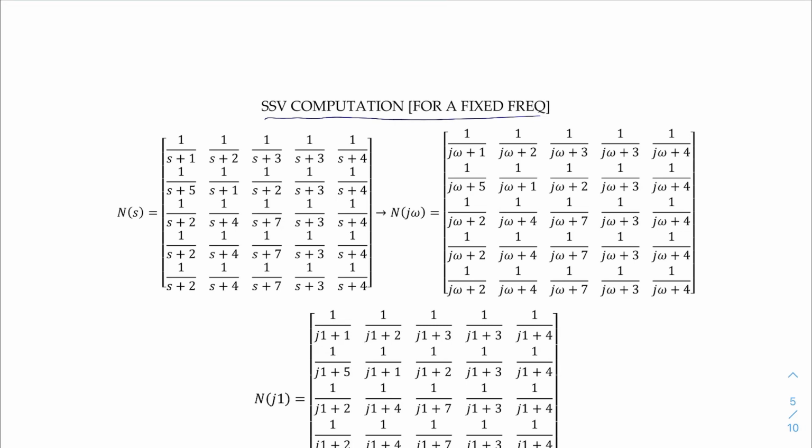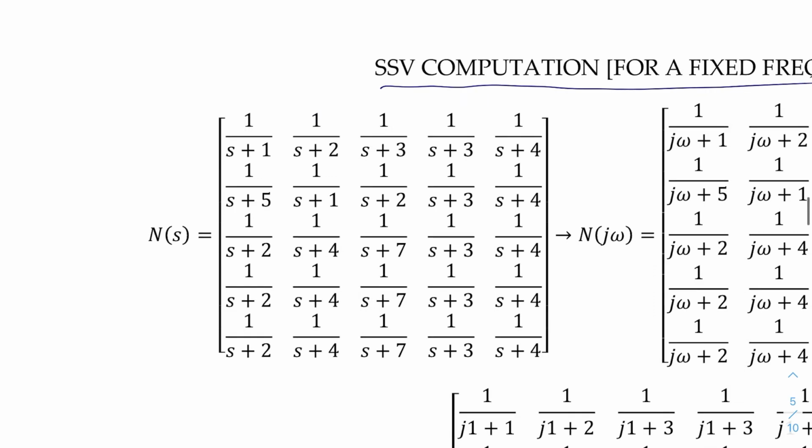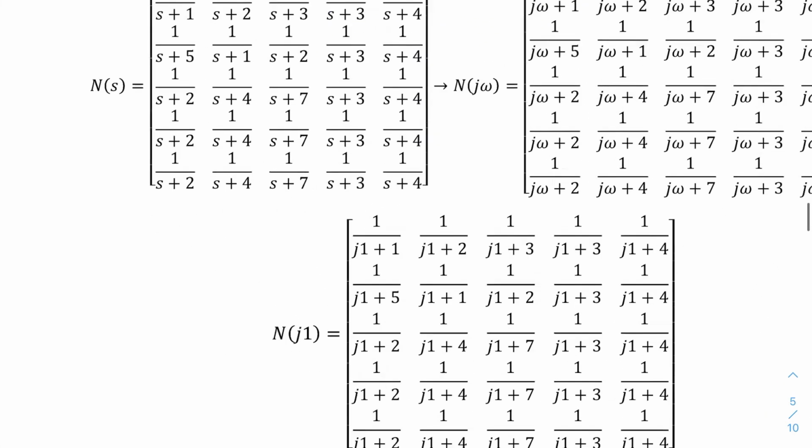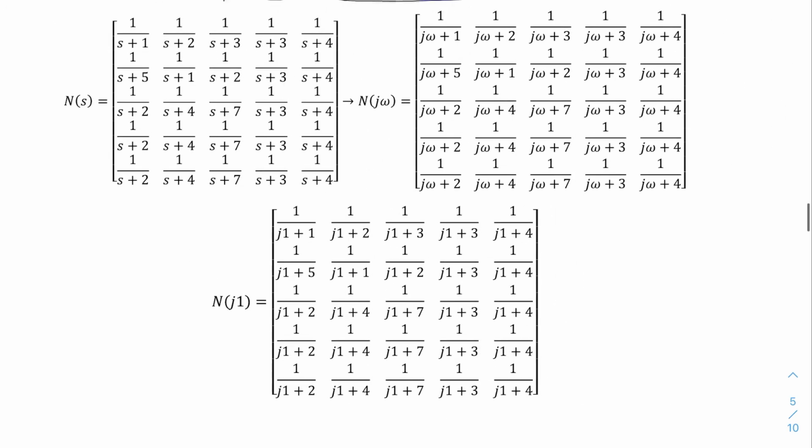Now we are going to look at case 4. Since it has mixed uncertainty, we needed a bigger dimension, and that's why I'm now considering this N matrix, which is 5 by 5. Again, this is the transfer function, and we are only looking at a given frequency, so at the end we have a 5 by 5 complex matrix.